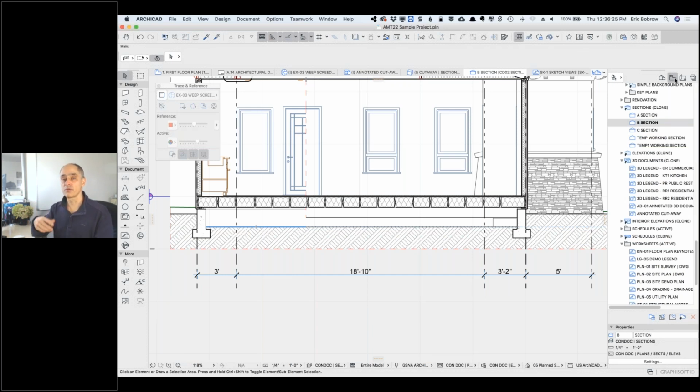Each one of the views has a viewpoint plus the layers, model view options, graphic overrides, all of these things that essentially allows you to reliably get things the way you want to see them, either for working or for putting into a drawing. So it's in the view map, and down at the bottom, there's an option to say save current view. This would save a view with this particular zoom, with these particular settings.